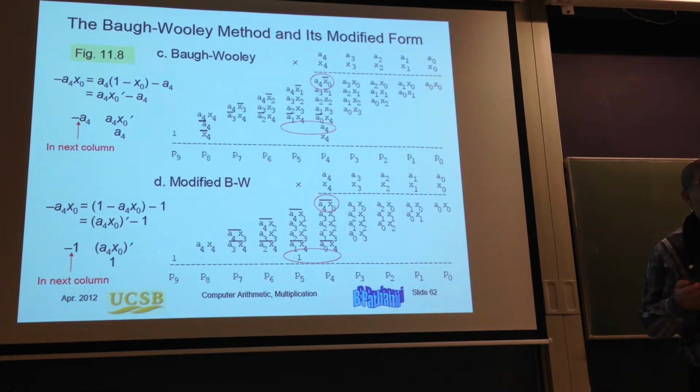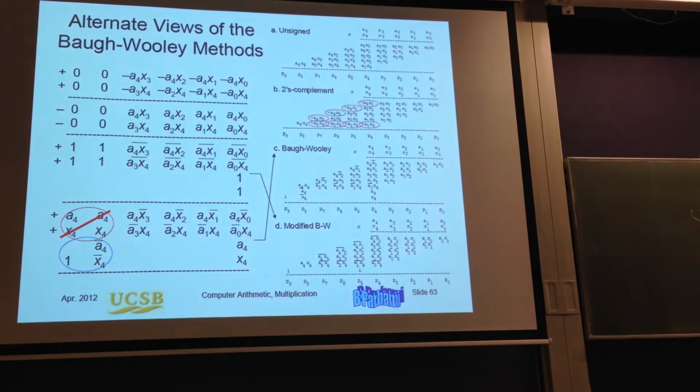If the height of the column is going from one interval to the next interval, I have a penalty of 1 full adder in my design. And then I should think if I really want to rely on this, or I should apply another solution. Okay? This is a way to understand it in a different way.